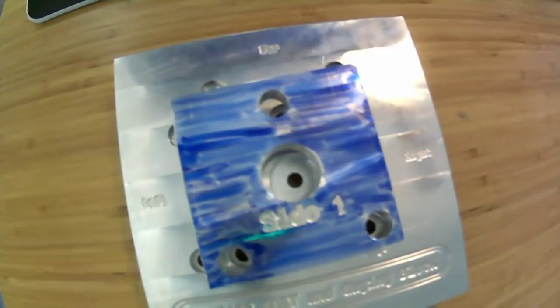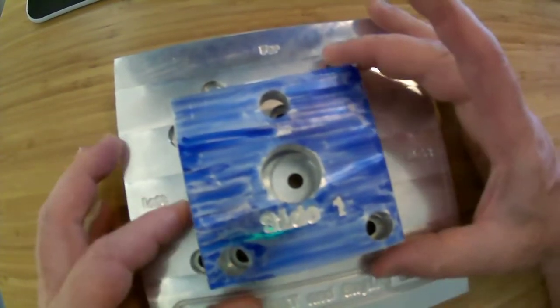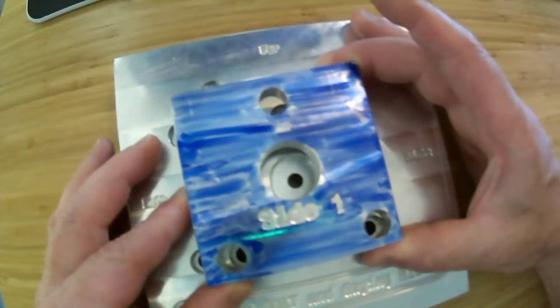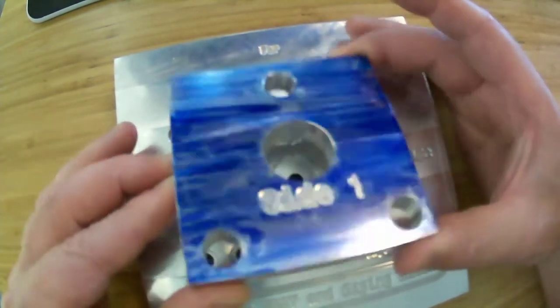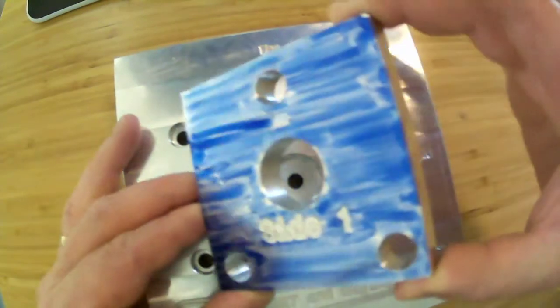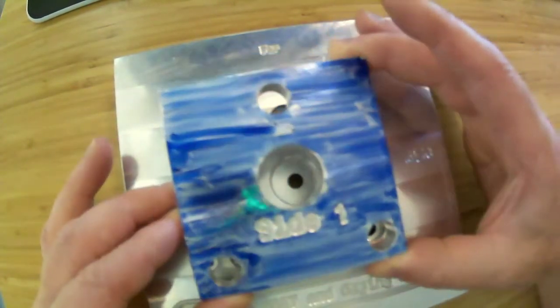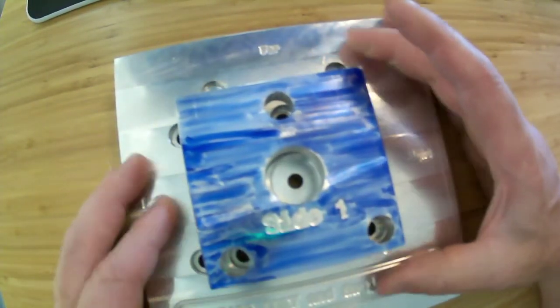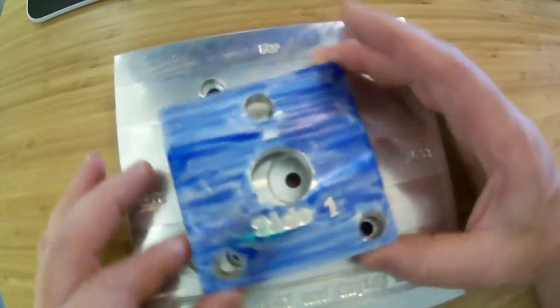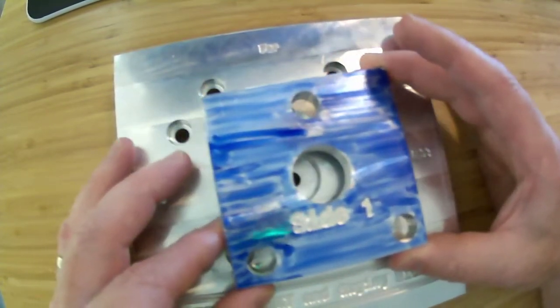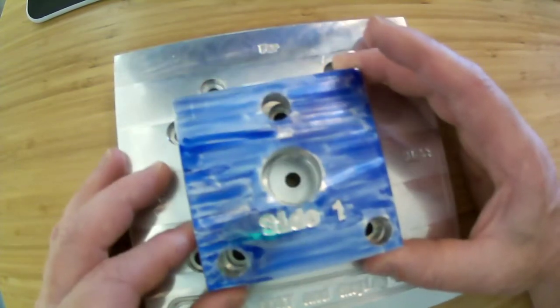When I put that on there, I have eliminated 3 degrees of freedom. It cannot move down in the Z direction anymore, and it can't rotate around X or Y anymore. All of those are taken out. So the things that it can do now are spin around the Z-axis, translate in X, and translate in Y.